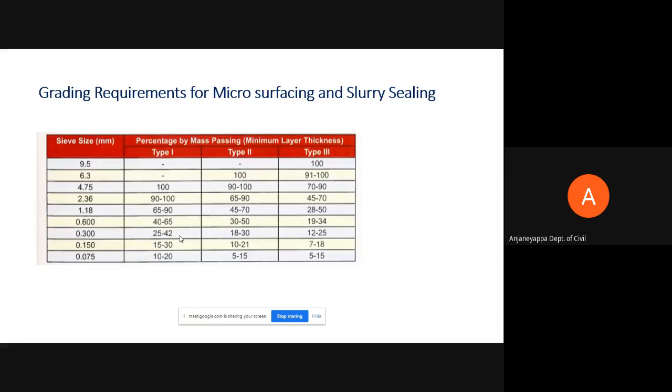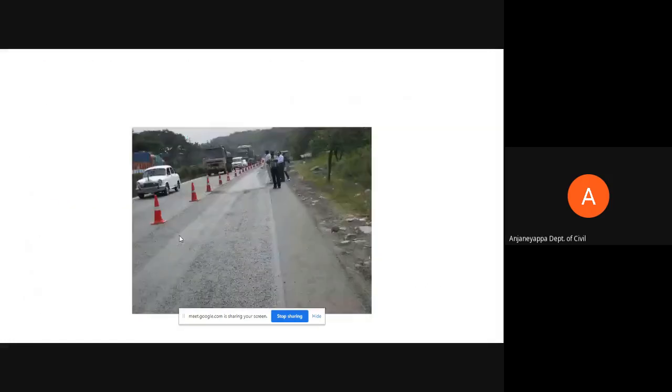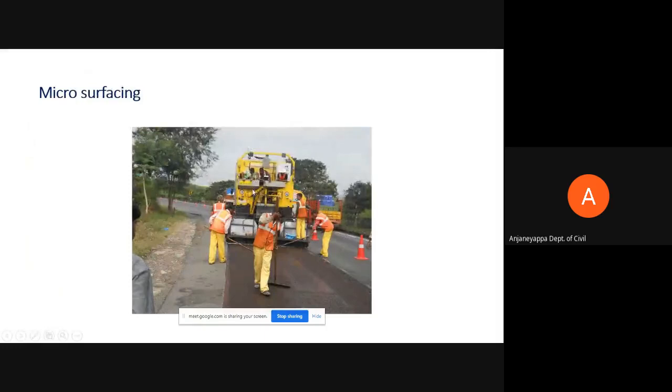This is new. Here and there we are using this microsurfacing. It's a self profiled machine. In this machine itself, this machine will have the emulsion tank, space for storage bins for aggregates, and a pug mill mixing unit, and the mix comes here and you have a screed here. The screed paves. No compaction is required, no paving is required. It is a machine itself attached with a screed, and the mix is prepared here. We have to load the emulsion, we have to load the required gradation of aggregates. So that's the advantage.